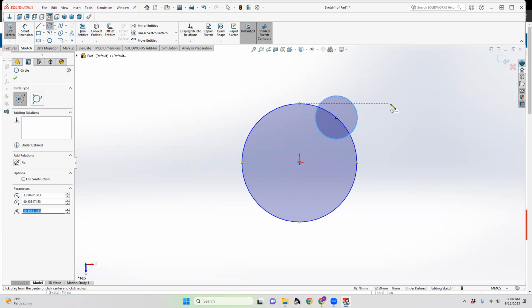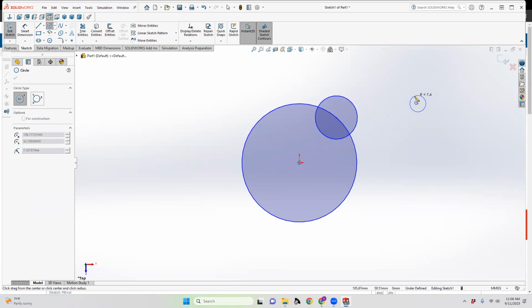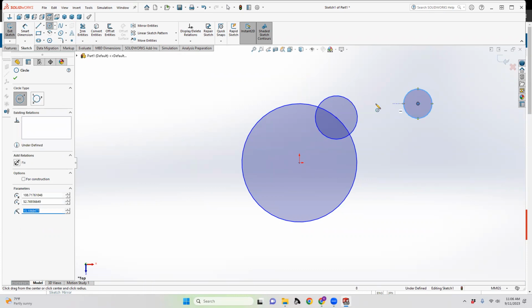And these leader lines will help you to set up something that is now parallel with something else. So you can reference a lot of different points. You can make it not only tangent to the circle, but you can actually make it perpendicular, or in this case, parallel with the origin, and concentric with the circle, or tangent to the circle, or all sorts of things. So there's a lot of properties we'll learn about in 2D sketching.